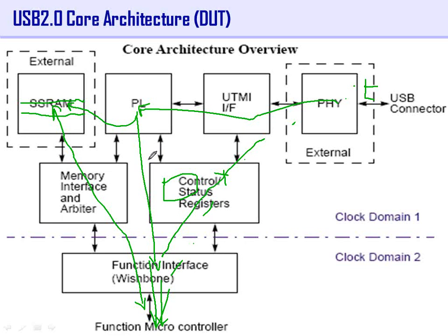Say 16 minutes to complete this, 10 minutes to complete this. Just that the time increases a lot. If individually it had taken 4 minutes, if you do it concurrently, it may take 6 minutes, right? It takes more time because a lot of additional work goes into this sharing, multiplexing, right? So each frame may have data packets targeted towards reading from the device, and may have another set of packets targeted towards writing data into the device. In one case you will use one endpoint number, in another case you will use another endpoint number.